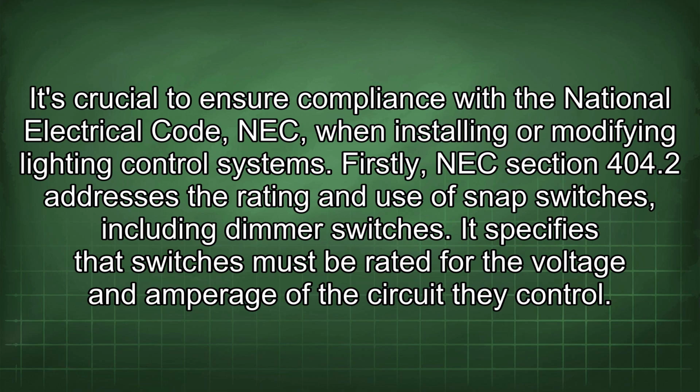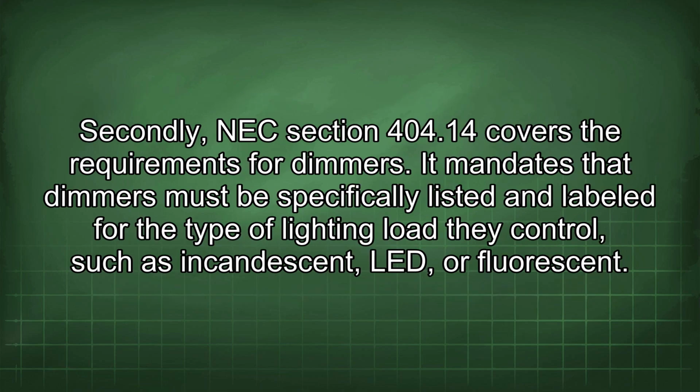Firstly, NEC Section 404.2 addresses the rating and use of snap switches, including dimmer switches. It specifies that switches must be rated for the voltage and amperage of the circuit they control. Secondly, NEC Section 404.14 covers the requirements for dimmers.